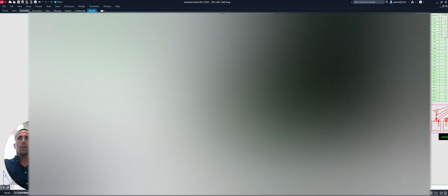The importance factor is 1.0. You can read about that in chapter 13 of the ASCE 7-16. Essentially the tank is holding air, which is not a hazardous material. And for our geotechnical data, we're going to say 1500 psf allowable soil bearing pressure because we do not have a report. Here are the standard codes that are applicable.